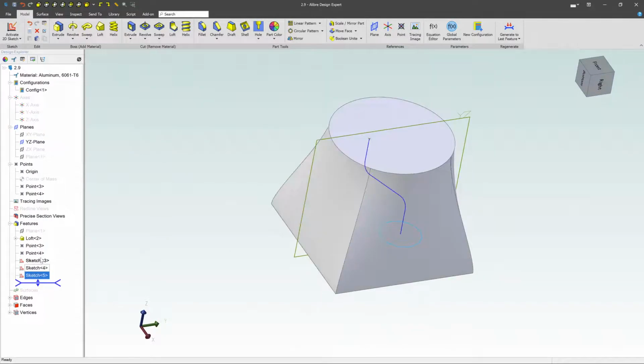All right, so I think I have everything that I need, right? I have the path that I'm going to be going through. I have the shape on the top. I have the shape on the bottom. Let's go ahead and create a little loft. And a lot of times if you're creating a loft, it will fail if you don't have everything set up perfectly. So you've got to make sure that you're double checking yourself and making sure everything is aligned and looking good and all the radiuses make sense for that shape to profile through.